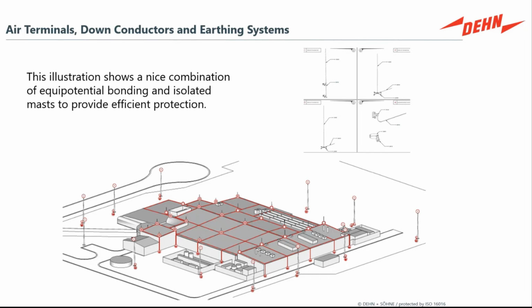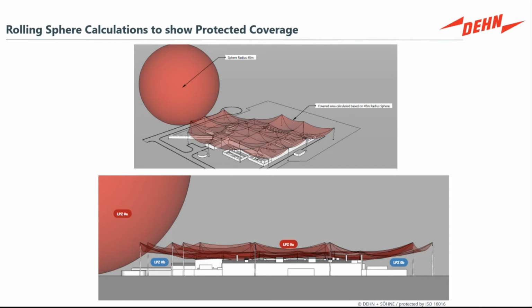So include it in the system, properly ground and bond it, and put up proper air terminals so that we're not obliterating the luminaire systems that sit on top of these light poles. This is an illustration of the types of models that we can apply on a structure and over the entire facility, to make sure you're looking at the entire facility at a holistic level. This would include all the transformers, any other solar equipment, these hybrid systems, power generators, and diesel backup generators. These all would fall under that zone of protection.